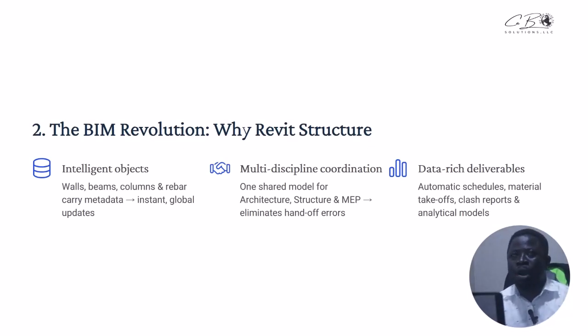For example, a wall in Revit knows that it is the host. Windows know that they are hosted elements. So when you bring a window close to a wall, it fits. The wall accepts it as an opening and the window fits into it. You get it? It is not some lines you are drawing to represent a wall. No, these are real intelligent walls. If you place a ceiling mounted lamp on a wall, it will not stick because it is ceiling mounted. So the elements are intelligent objects. They understand their function. Do you get it?